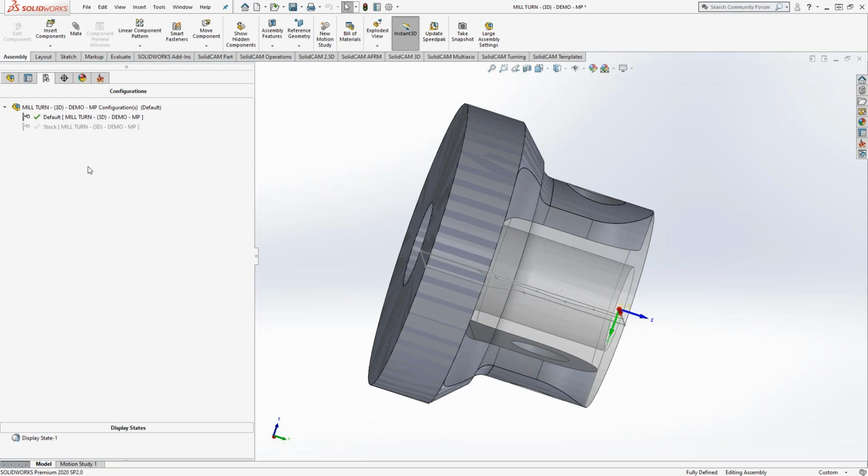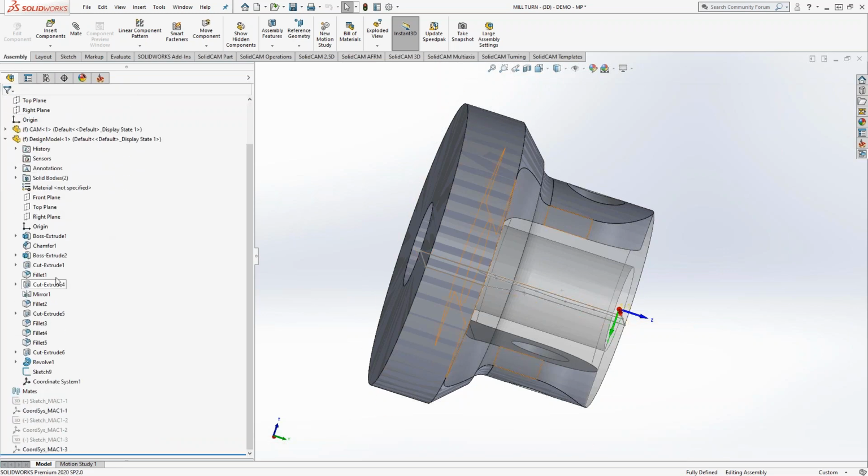That's easier. Yep. I would say from the part that you described, Frank, it probably would be easier because in your SolidWorks part, you can suppress whatever slots, whatever pockets, whatever flats you have, and then you have what looks like a turned part. It doesn't necessarily have to be all kinds of features like I had here, where after a certain point, it's all mill features. It could literally be the fillet, the chamfer that you're adding, any holes you're drilling out, anything that you have peppered throughout your feature tree. You can actually suppress them individually and then only leave behind revolved features. Anything that you did a revolve or an extrusion of, you can suppress anything in there and then just save that as a type of configuration.